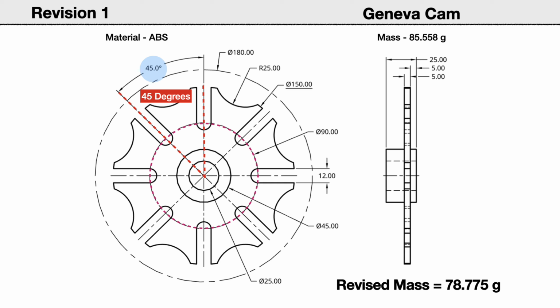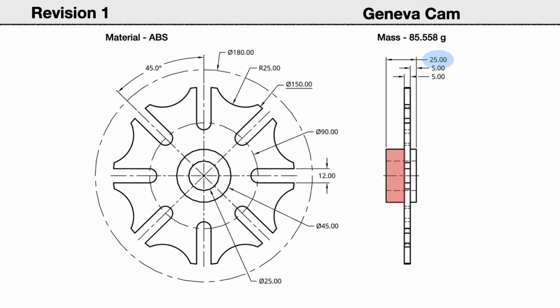The number of instances of the circular pattern is changed to 8. This changes the angle between the slots to 45 degrees. From this, we can calculate that the center of the arc is now 22.5 degrees from vertical. The radius of the arc is now 25 millimeters. Also, the depth of the front hub is now 20 millimeters. This distance is measured from the back of the plate.